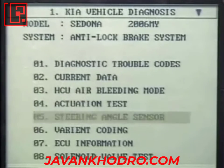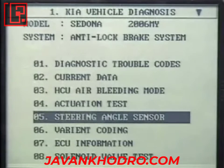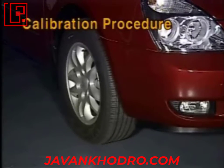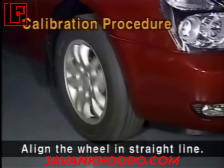When the steering angle sensor is replaced, the current position of the steering wheel is sent to the scanner using the calibration by scanner. The method for calibration is as follows. First, align the wheels in a straight line. Drive the vehicle backwards and forwards 2 to 3 times.